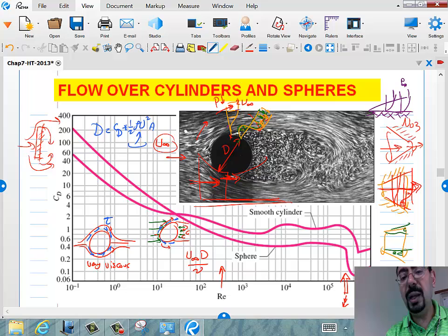Okay? But then in this part, now it's a diffuser, and the velocity is decreasing and the pressure is building up. So if the pressure builds up very quickly, the flow will say, I'm not going to decrease my velocity. It's very hard for the flow to go against that pressure. Right? And so it will decide that, no, it's easier to go this way. Let's just go this way and leave this place where the pressure is supposed to build up.